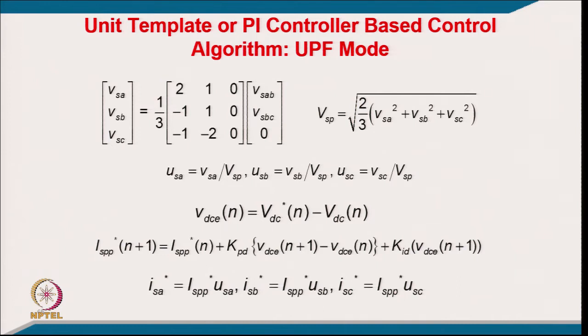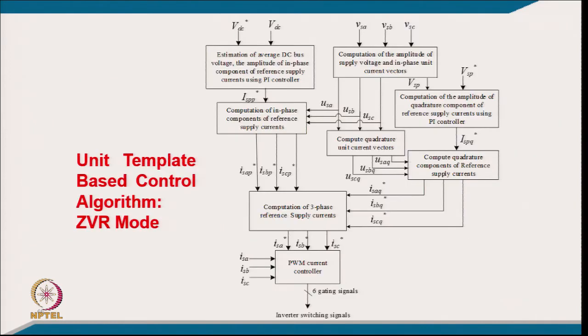So, we sense the grid current and put a current controller, either a hysteresis current controller, a PWM current controller or an on-off current controller. There are plenty of current controllers which are used on these current errors. So, this is typically the block for 0 voltage regulation.